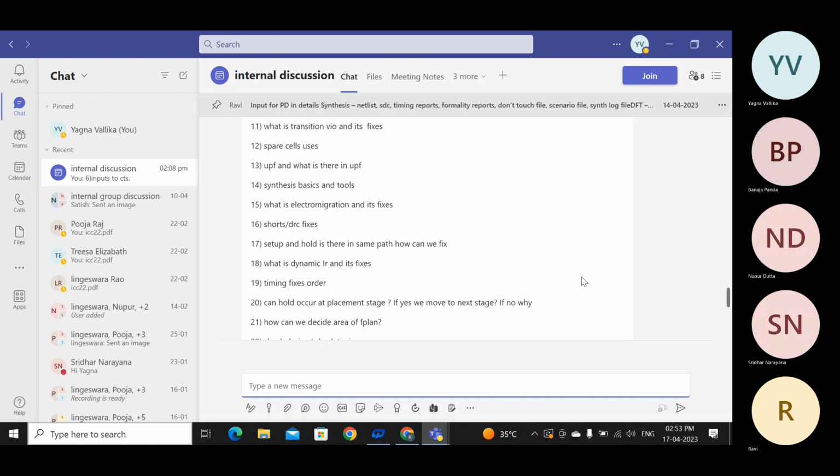specific to that. So what will be present in UPF is which power domain connects to what, okay, and if you want some specific level shifters, you can define them. You can define basically all the power connectivities and isolation, type of isolation required, whether it is AND isolation, OR isolation, etc. All those things have to be defined in the UPF. Okay.